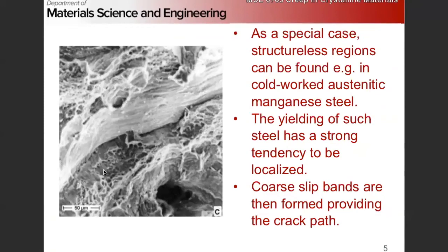These slip bands here become a weak point where you have very easy fracture, with a tougher ductile region here. So these slip bands form an easy crack path through the structure.